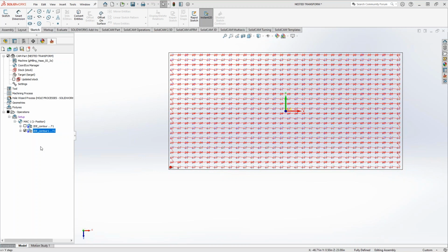Now, and you'll notice, sorry, Kevin, go ahead. I was just going to add to that, if you guys are running also, it doesn't have to be the same part. What Mark can do in here is he did a SolidCAM new milling on this particular part, but you can add multiple different targets in here and then do that as a pattern too. So if we had an L shape and then maybe a T shape and then maybe an A shape that we're pocketing out, those are the three components that we want to put on here. Put those on there as the target model and then go through the same process as what Mark was just showing you. So you can have multiple different targets in here and keep copying that over to fill up the space that you have, in this particular case, a 4x8 sheet of plywood.